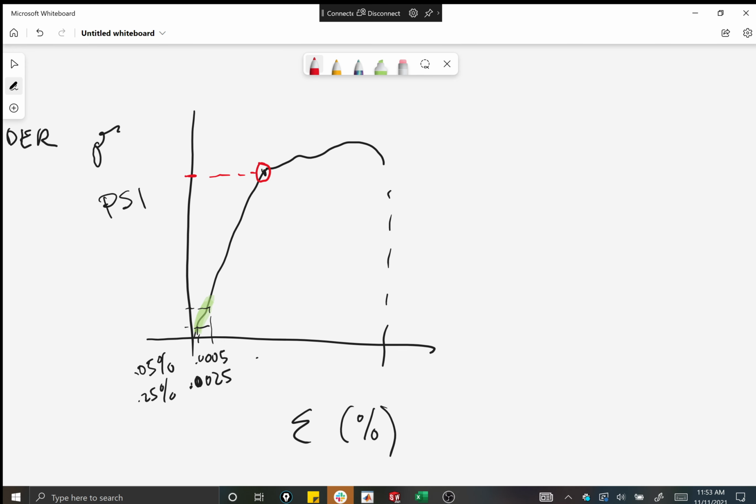Johnson decided that, because he put that in the equation. It also makes sense because we're saying in structures, we always want to keep below the yield point when we're designing things, because once we get past this, it may not fail, but it's going to be damaged, and now it's a new thing. It's not static anymore, right? Okay, let's keep going on this. So obviously yield stress, loading, that could be loading. What's the load at the proportional limit? I mean, that's maybe a little bit tricky, but that's load at yield.